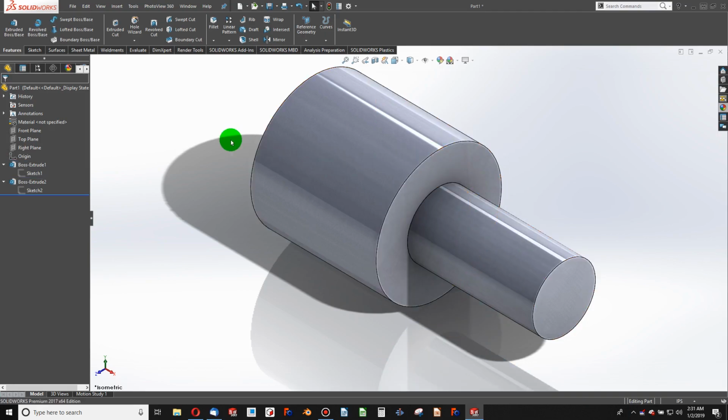And so all of your fillets and chamfers and everything that you might put on an edge will update no problem. It's just when you are working off of an existing plane that will need to be manually updated. So hopefully that's clear as can be.